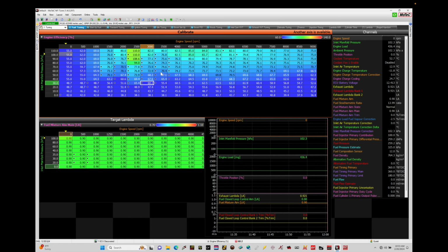The idea here of what we're trying to accomplish will be the same as other standalone systems, meaning when we have a large throttle rate change, so our throttle opens very quickly, we're going to have a momentary large burst of airflow, and we need to match that with a momentary large burst of fuel pulse width so we don't have a lean tip-in condition. It can create a lot of drivability problems for us. That's going to be the general approach across every standalone system, even factory ECUs.